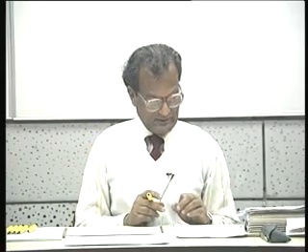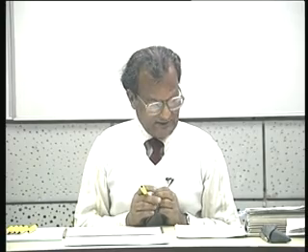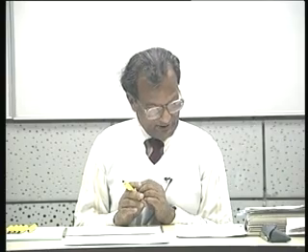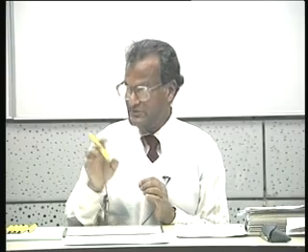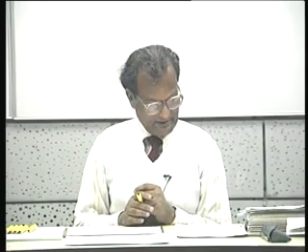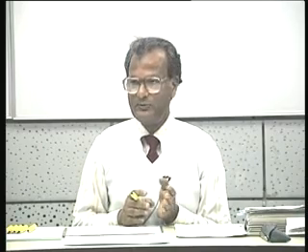Then the second part says that this single tuned circuit is inductively coupled loosely to another identical single tuned circuit. Now, we come to the case that was discussed in the class, a double tuned circuit, and the output is taken across the resistance in the secondary. This is precisely the case that we dealt with in the class. The magnitude response shows 2 peaks, one of which occurs at 110 radians per second. Well, one of which means it must be the upper peak. One greater than omega n is the upper peak, one less than omega n is the lower peak.